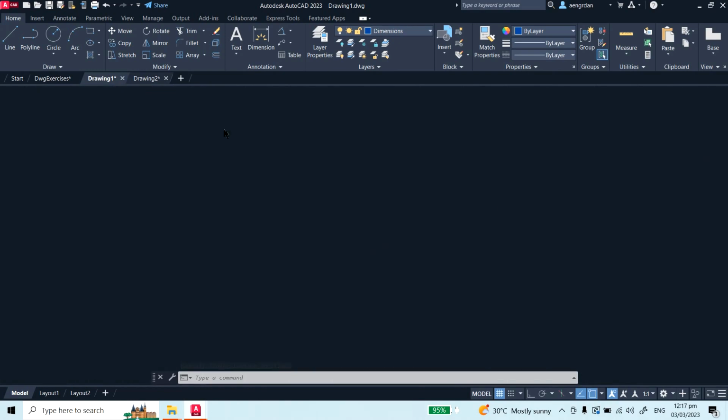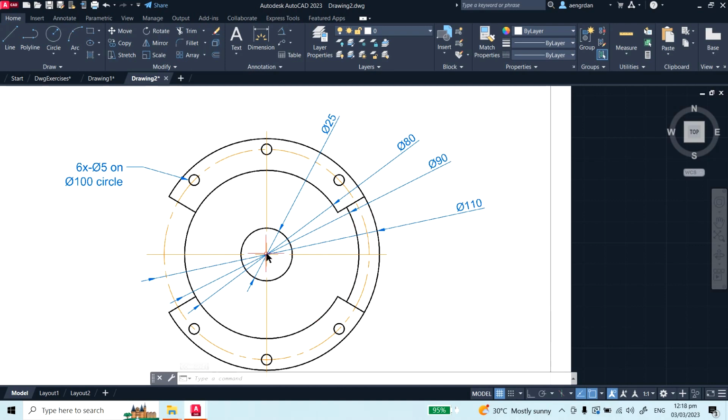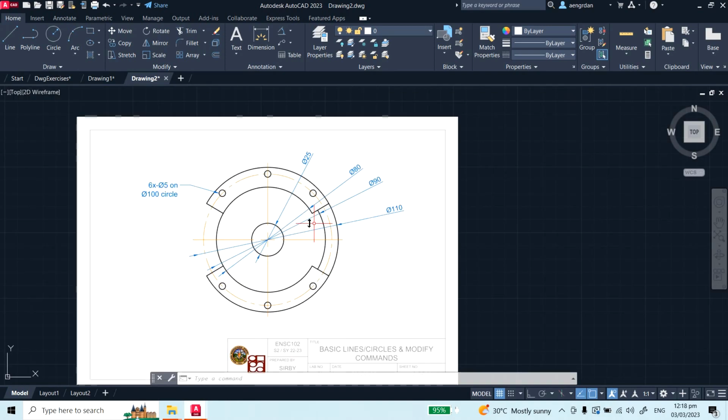Okay, next one is this. So again, analyze. It's almost the same. We have concentric circles and we have some arrays here. We can do arrays because 1, 2, 3, 4, 5, 6, except that in this portion we can just delete this. We array these small circles into 8 items, I think, because 1, 2, 3, 4, 5, 6, 7, 8. And then just simply delete this portion. Okay, so I think that's the best option.